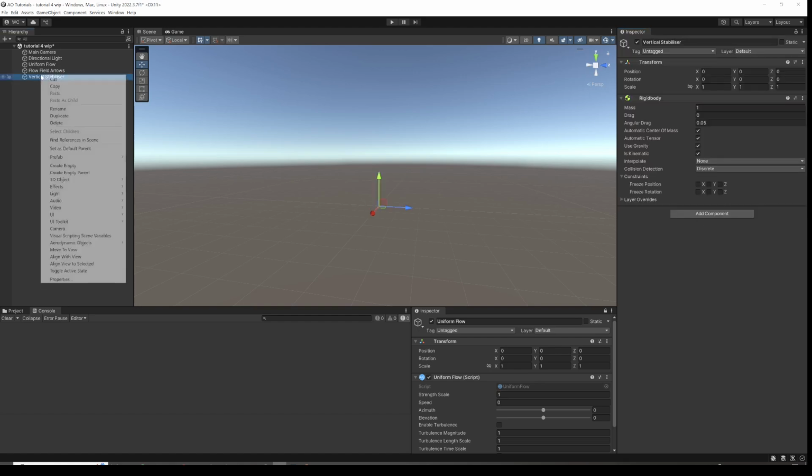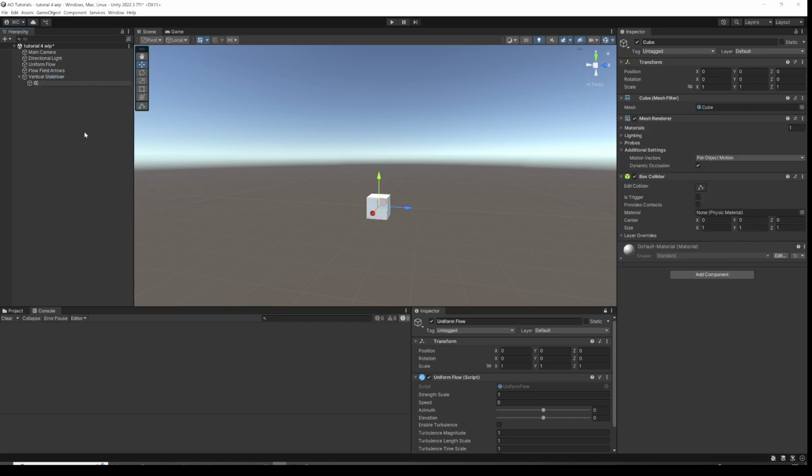And as in previous tutorials, we're going to do the same process for building things up. So we're going to add some geometry in. We're starting with a cube, but this time we're building a vertical wing as opposed to a horizontal one, and Aerodynamic Objects doesn't mind about that, but this is for us to make sure we do things the right way around. And we're going to make it 3 centimeters thick, 2 meters tall, and 0.7 meters chord.